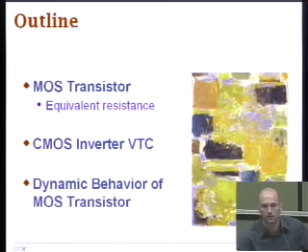That's one of the ways you can increase your resistance, by increasing the length. If you have a long channel, then the resistance of your driving gate will be higher, and the capacitance of the load will also be higher due to a larger area. You will have somewhat higher current because of the quadratic benefit, but they kind of turn out in favor of short channel.